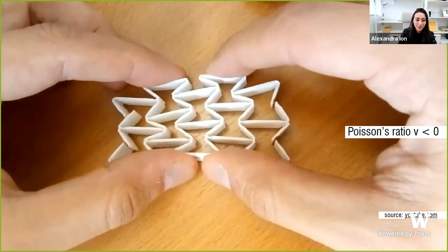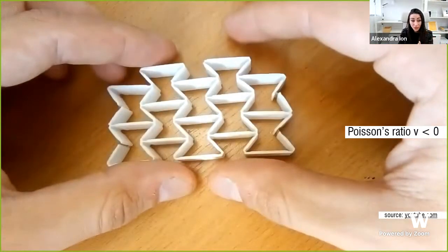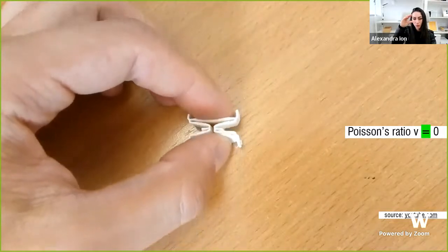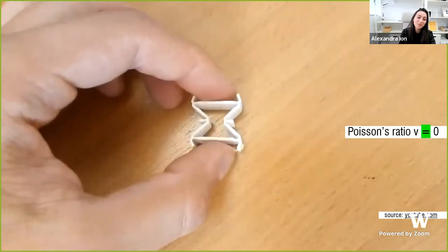So what's interesting about this is that this works if you have multiple of these cells put together. If you isolate just one of the cells here, it doesn't have that property. It actually has a Poisson's ratio of 0. So you compress it downwards and there's no contraction on the orthogonal dimension. So that is something that I find really interesting, not only that we can engineer these properties, but we can also embed different geometry, different functionality into these structures by arranging those in an interesting manner such that they work together to fulfill that function.